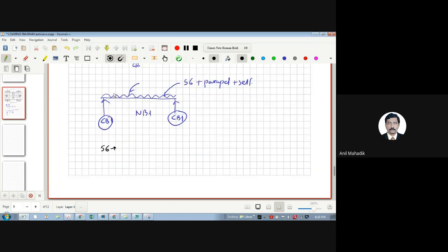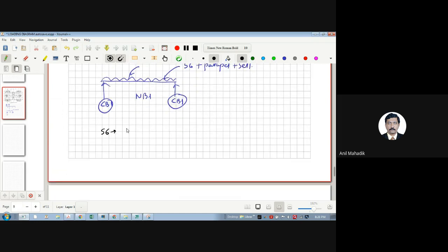Suppose sunk is 8, floor finish, screed plus tile, is 1.5, and in balconies we have live load as 3. All of you know passages and balcony. So roughly it is 13 kilonewton per meter square. It is a slab load. So this is your live load, this is your floor finish, and this is your sunk.